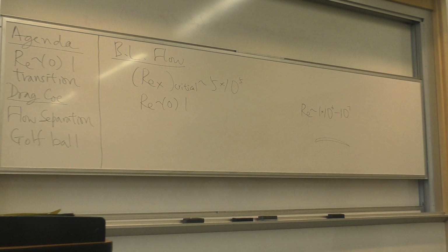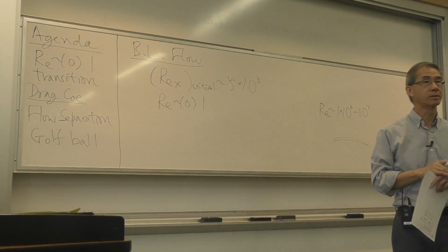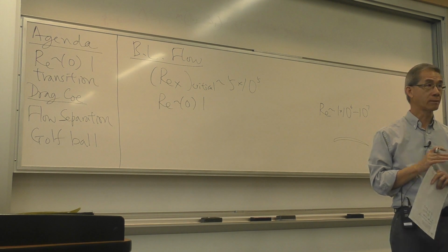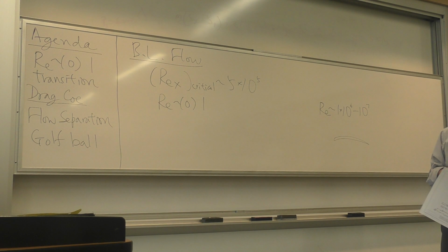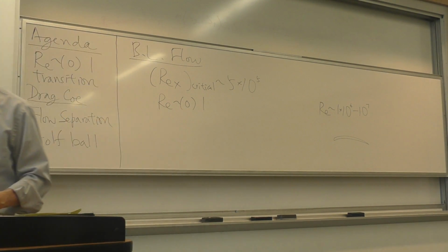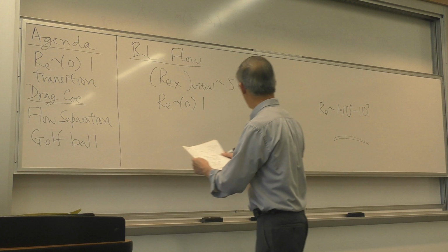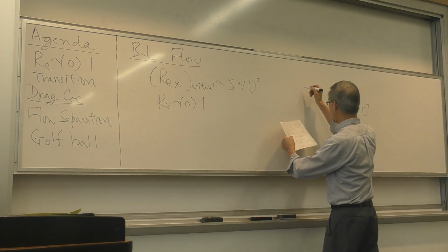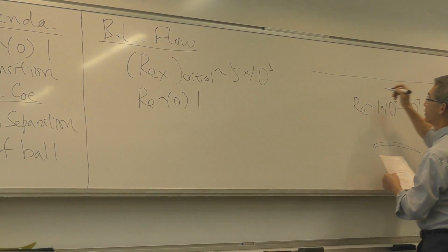So for the external flow we are dealing with in chapter 9, there's always a laminar flow to start from the very beginning of an object like an airfoil, a flat plate, a car hood, etc. So I would like to relate this concept to your homework that's due today, to estimate the boundary layer thickness on a car hood.